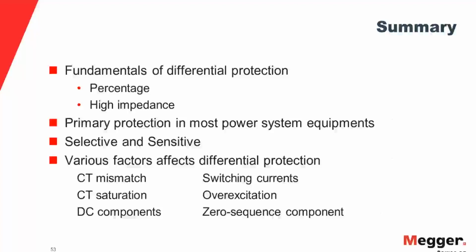On top of that, all the tests that I mentioned before, like a true fault test or an external fault, a timing test or a pickup test, the slope test, and the harmonic block or restraint test, you can do all of these automated as well. We have built-in curves along with the slopes. We have built-in timing curves for almost all the relays available in the market, so you can verify your time coordination studies.